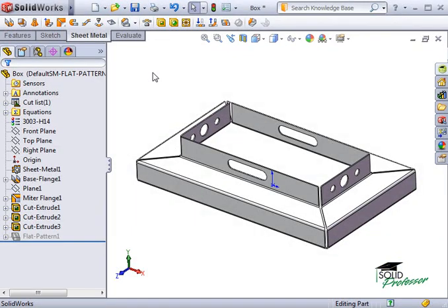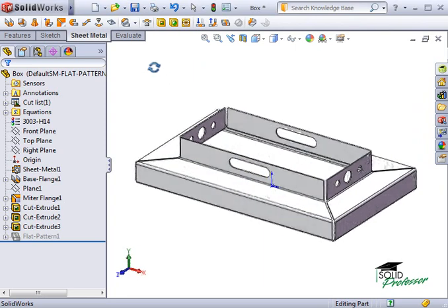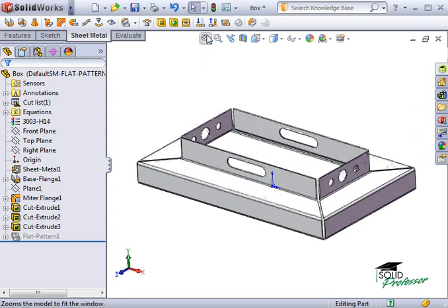You've probably used the Mass Properties dialog box when designing parts to check the mass properties of your parts, such as mass, volume, and center of mass. Well, a new set of properties specific to sheet metal designers has been added in 2011 that you might be interested in. These new properties mostly pertain to the flat pattern of the sheet metal part. So before getting started, let me flatten this part here.